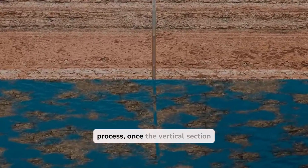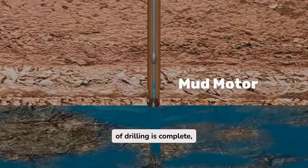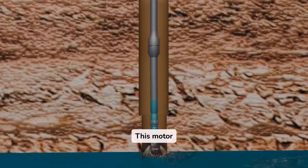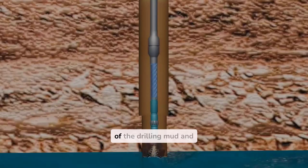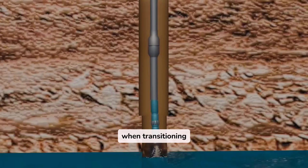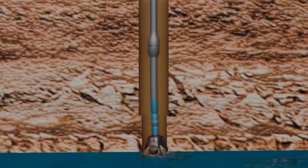During this process, once the vertical section of drilling is complete, the drill bit is removed and replaced with a mud motor. This motor operates independently using the pressure of the drilling mud and does not require the entire drill string to rotate. The most remarkable feature of this motor is that it can be slightly tilted, typically by around 1 to 3 degrees, when transitioning from vertical to horizontal drilling.